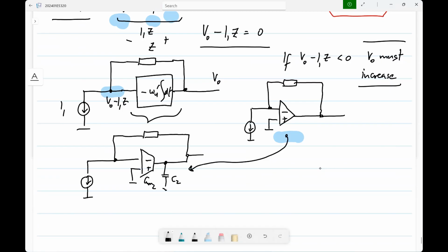Is this logic clear? So that I to V conversion itself is realized using negative feedback, and for that negative feedback you need an opamp, and you use the only opamp that you know so far, which is the single stage opamp. Is this okay? Any questions? So first of all, this circuit itself, is it familiar? This one?